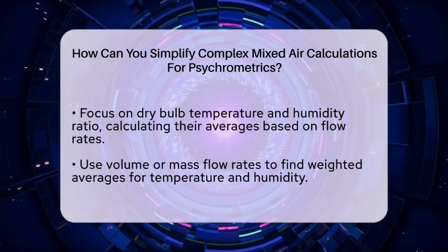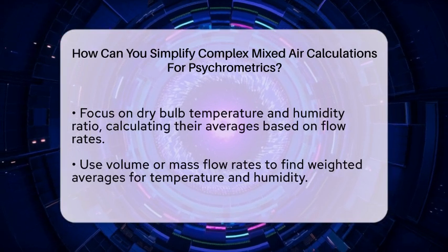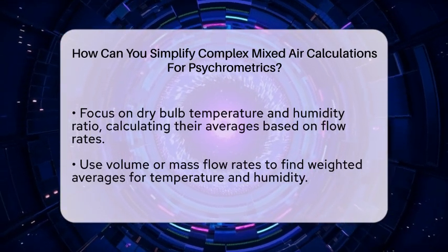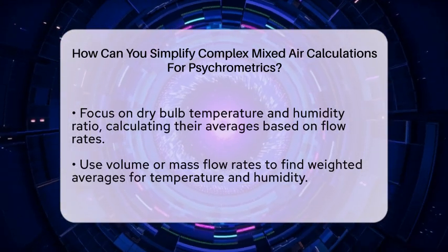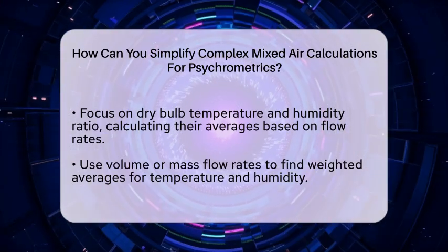If you know the volume or mass flow of each airstream, you can find the weighted average easily. For most HVAC applications, volume-based calculations are enough, but for more precise work, use mass flow rates.